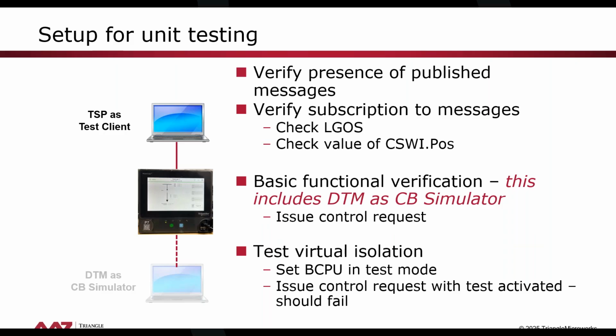But then in the next step, we want to do some basic functional verification. And in that case, we need to have something that simulates our breaker. And we are using DTM in that context to simulate basically the interface to the breaker and the breaker operation itself. So we'll do a small test there, just trying to operate the breaker and see that it performs correctly.